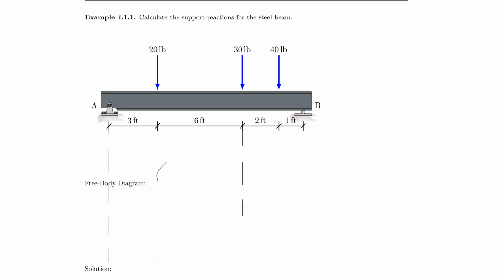And here we go. My next force and the end of the beam. And then I have to draw my free body diagram. And remember what we talked about, that the free body diagram is now representing a rigid body, and a rigid body always has a dashed line to identify it. You will learn more about this later, but for now just apply a dashed line on the bottom. Sometimes you can put it on the top later on, but for now just put it on the bottom.